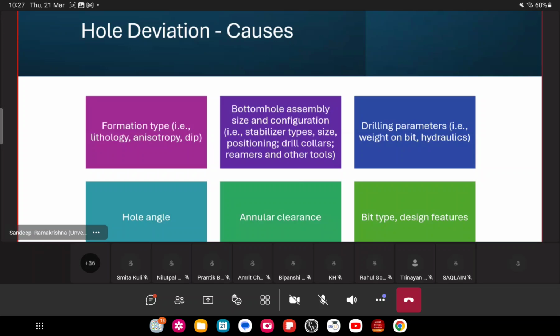And it includes all kinds of equipment that is there at the bottom, right? If you are in a deviated well bore, we talk about positioning that well bore, and there are many ways of positioning it. We talk about downhole equipment. That's what I highlighted last time. But there are simple things where people use bent subs and the distance between the reamers and the bent subs and all these things, which can help to drill and position that particular wellbore in an angle.